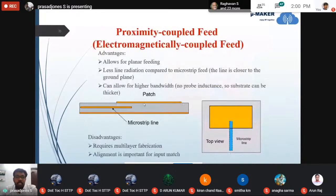And then with respect to proximity coupling, the microstrip line is sandwiched between two dielectrics. On top of the dielectric is the patch, and at the bottom is the ground plane. Through the coupling only, the patch is excited.